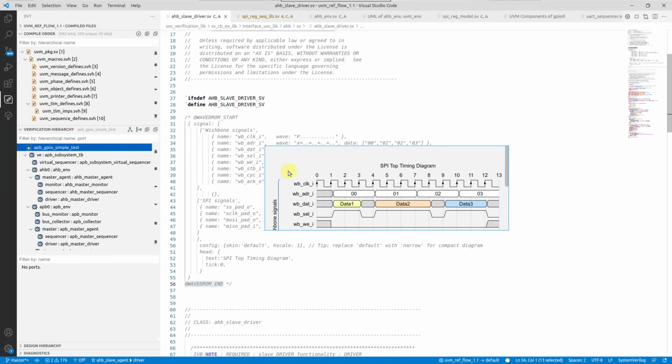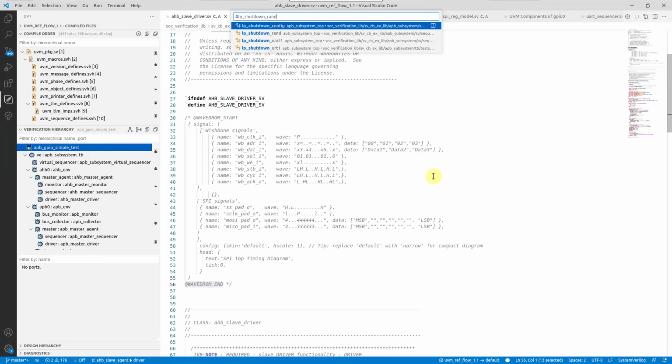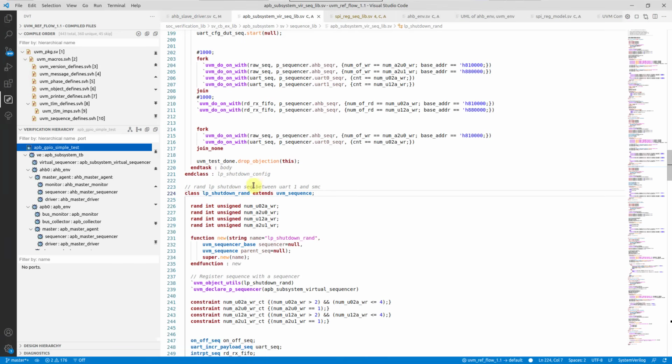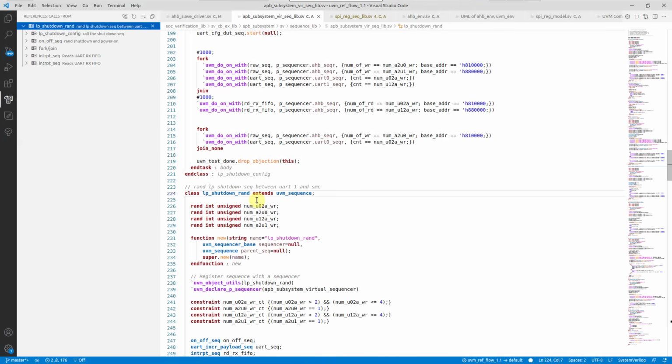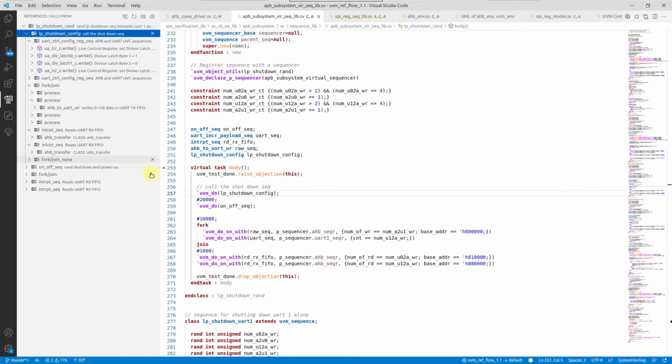Since we're here, let's talk about another useful Testbench Exploration feature, the UVM sequence tree. Start from a sequence of your choice and run the Show UVM Sequence Tree command. The References view gets populated with the sequence call hierarchy, showing all the subsequences and transfers driven by it. For easier understanding, DVT also displays next to each entry the associated comments collected from code. Click an entry to reveal the corresponding source in the editor, for example, the UVM do macro call.